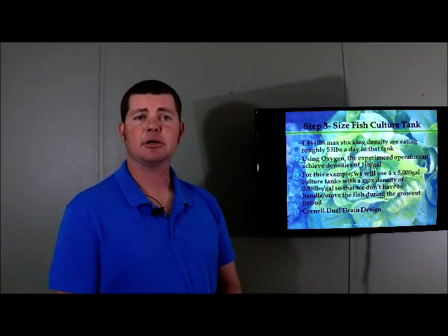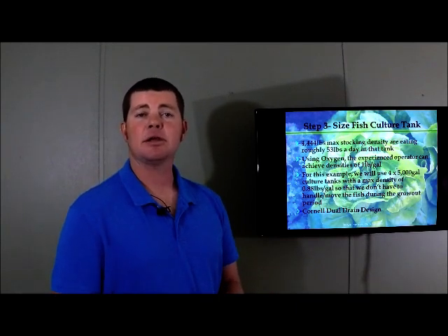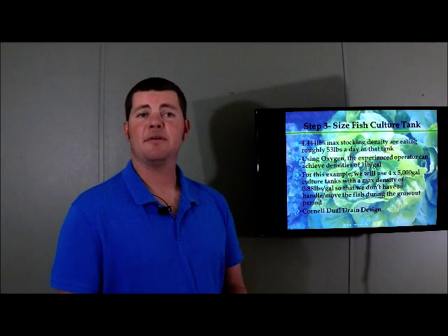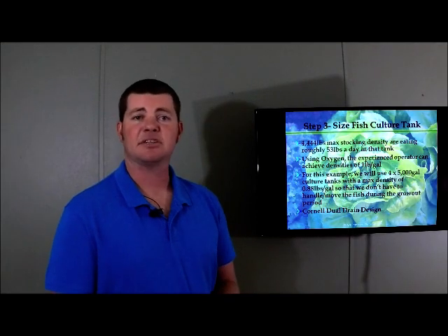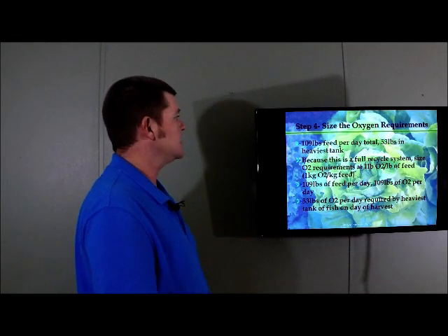Because we're utilizing pure oxygen, we can more efficiently collect and remove those solids through a center bottom drain where we send part of the flow. We send the rest of the flow out of a sidewall skimmer box, as we've talked about in that part of the lesson.